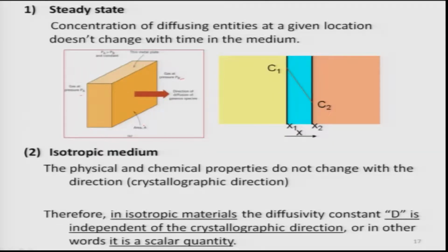And if I plot in one dimension, because we can always assume this is happening only in the x direction, this is what will happen to the concentration difference at x1, on this side, and at x2, on this side, and there is a concentration gradient. You can see here del c del x is present, but this does not depend on time. This is completely a steady state thing, so it does not depend on time, and we can use that flux is equal to minus D dc dx. This is what we used to see, all metallurgists or material scientists, such derivations of the flux.